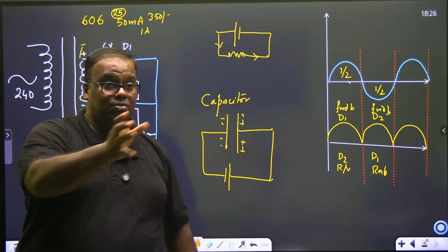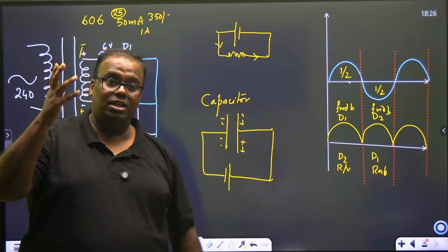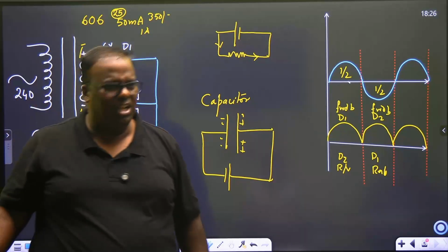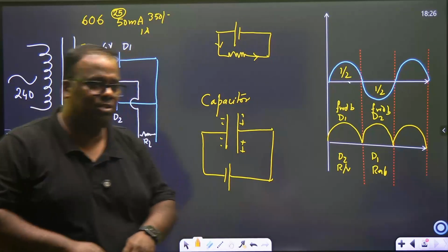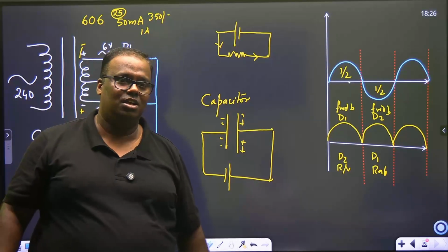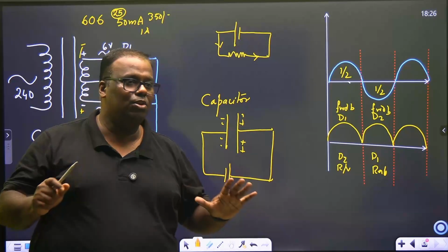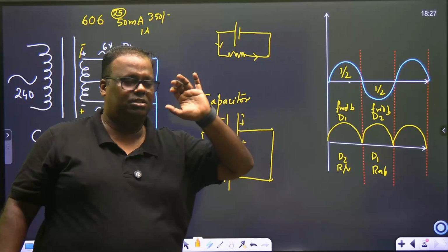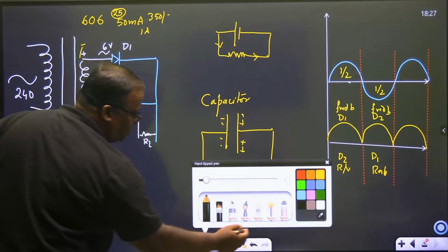Microwaves have got built-in capacitors because they are needed to generate that high voltage. And if your microwave goes bad and you have put up a complaint, the technician usually in our city will come 2 दिन बाद. The first thing he will do after opening the microwave is take his screwdriver and short these two. That capacitor stores the charge almost till 4-5 days also. It will be fatal for him. The first thing when you open a microwave is to short the capacitor. Fans have got capacitors. Touch करके sound करेगा. They store charges. So here what we do, we bring a capacitor for our rescue.